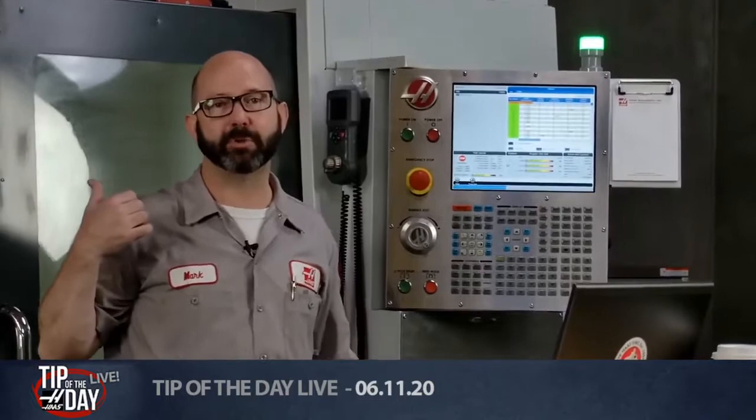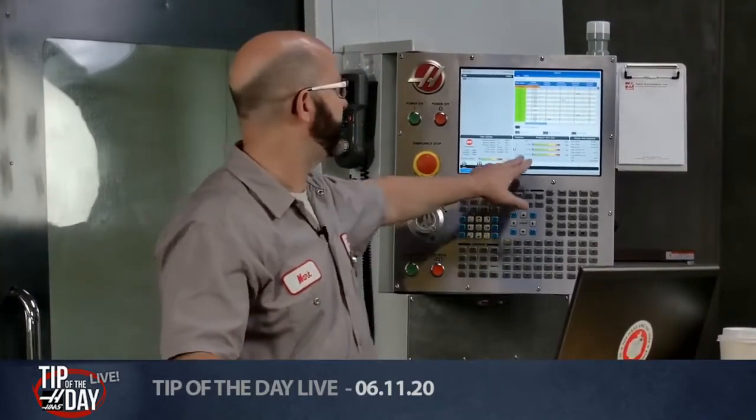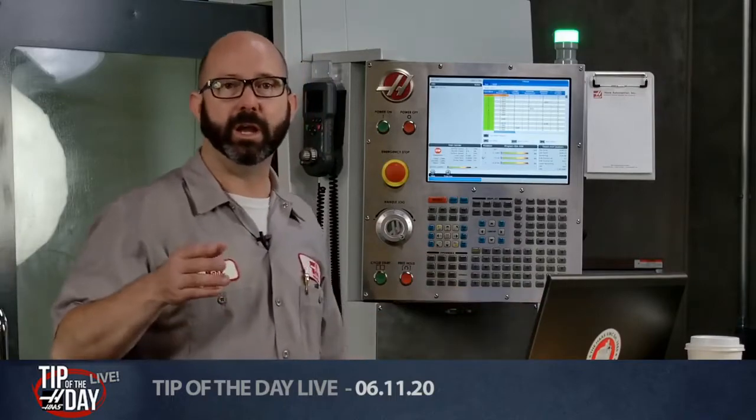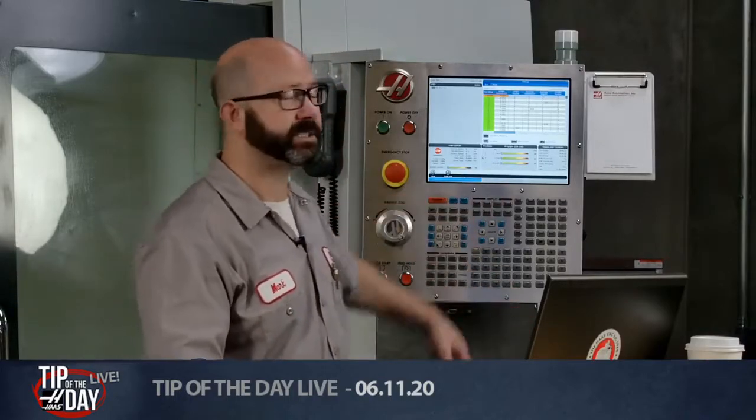Now on this machine, my probe is set to 25. On our UMC, it's set to 41. On the tool offset page on a next-gen control, you can define what type of tool it is. You can set it to, number 1 is a drill, number 4 is an end mill or a shell mill, 3 and 4. Number 7 on the far right of that list, you can set the tool type to probe.